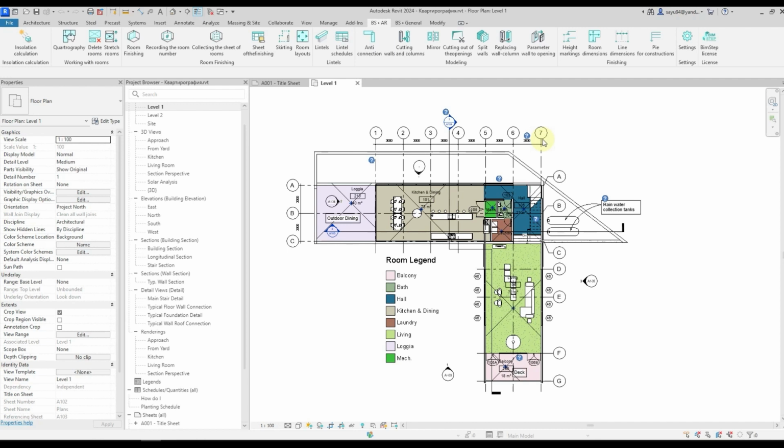In order to calculate a certain area for each flat, that is, how much you have living space, total floor area, or floor area including balconies and loggias, you need to count the apartment calculation. An apartment calculation is determining how many square meters your living area is, the total square footage, and the square footage including loggias and balconies, but the loggia and balcony participate at certain ratios. Basically, the loggia has a coefficient of 0.5 and the balcony has a coefficient of 0.3.